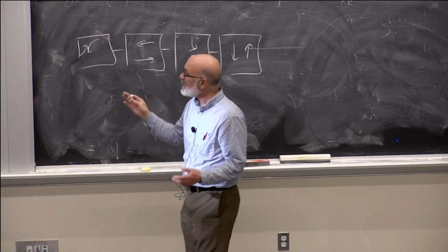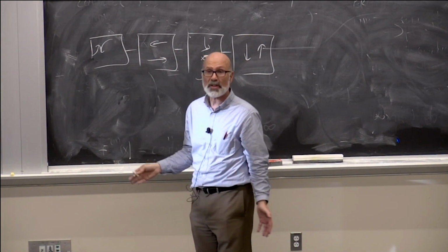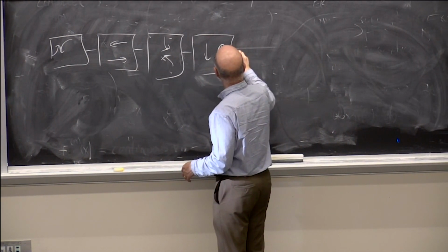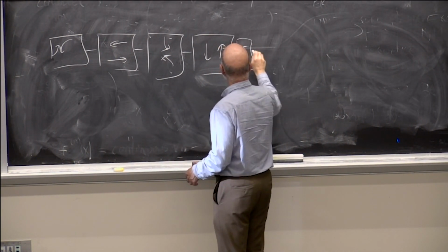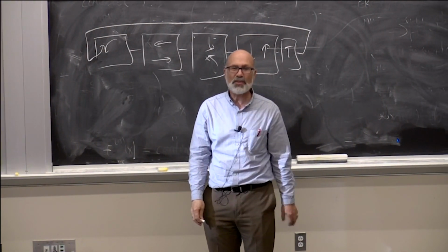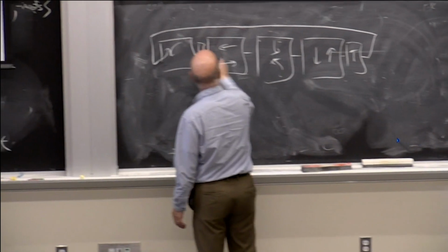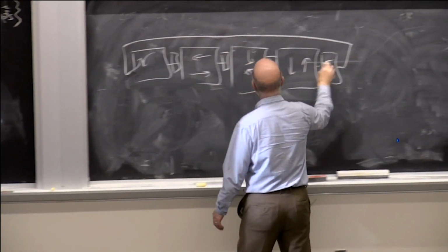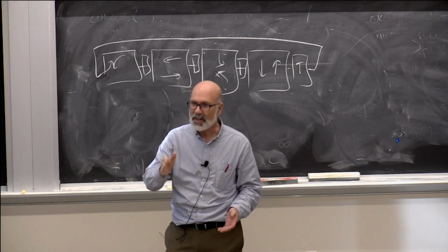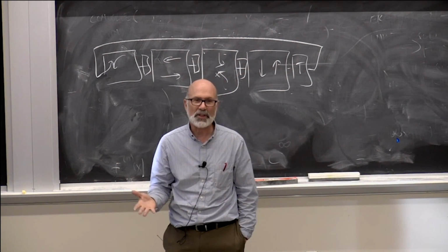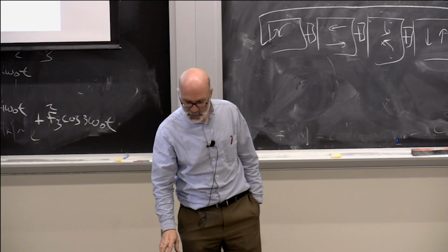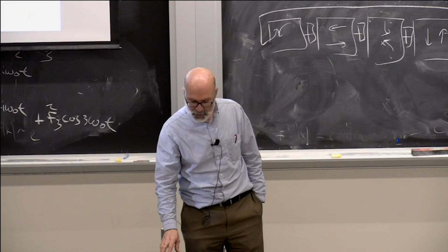And the tram, in this case, actually conflicts with all of them. So the normal thinking of a traffic engineer would be, okay, we'll have a tram phase here, and now that's the cycle. But the Delft thinking is, we'll put a tram phase here, here, here, and here. And if there's no tram, well, we skip it. And if there is a tram, then the tram gets to go. So the tram never has to wait long. So that's part of, if we can get a man on the moon, we can turn the light green.